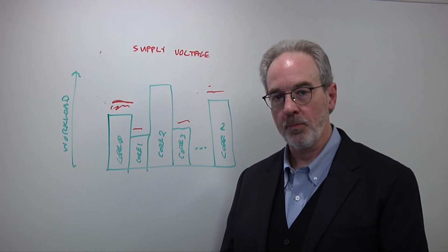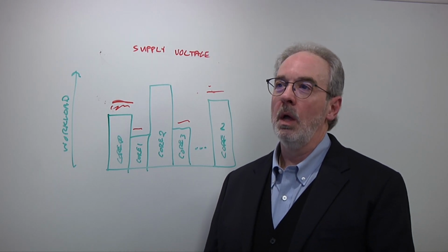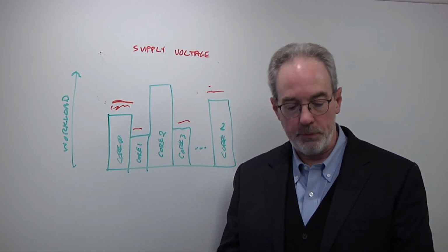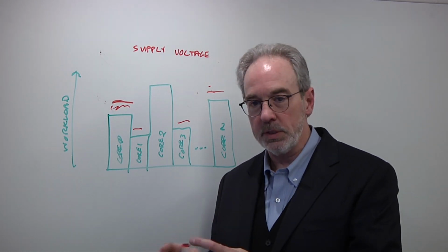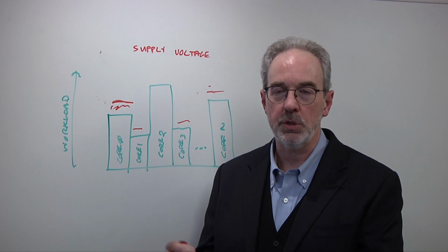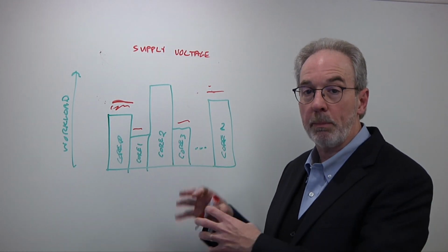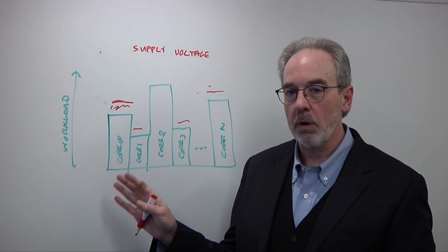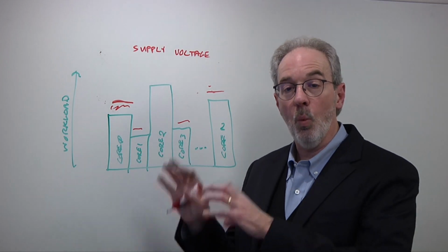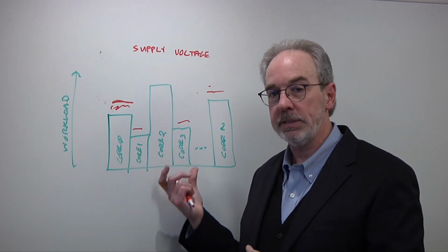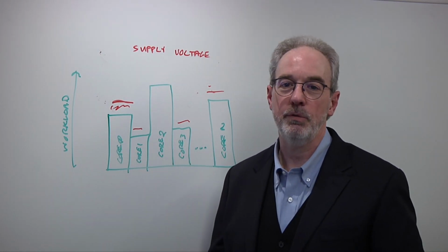You know, when you look at this, you think about LDOs, and LDOs have been out there for a long time. Why haven't they been used here? The reason is applicability. If you think about an LDO, typically they're designed to provide a low amount of current to a small specialized piece of circuitry with high noise suppression. You're talking about currents in the order of hundreds of milliamps. Here, because we're driving the voltage per core or per cluster, we're talking about currents in the amp ranges. So they just typically don't apply. They're not quite the right solution. Once we have the ability to drive higher currents and still do the local manipulation, then this technology becomes applicable and really exciting to allow customers this degree of freedom.